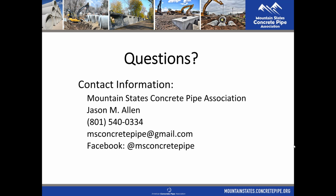All right. Joey asked a great question: what if they need to lay it at a very precise elevation with very little slope? I'm assuming this is in response to the loosely placed bedding question. That is a great question, Joey. As contractors are laying this at a precise slope, you're giving them the finished grade, right? And you're telling them where to install this. If they're loosely placing it, they're not going to place the grade of the bedding where it needs to be plus 3 inches, or whatever it is.